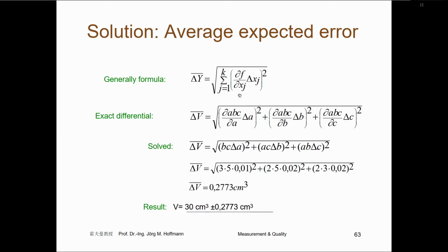But when we do not have a standard deviation, we take this other determined value, the delta of the error, and we calculate the average expected error. Here it does not work to double this. You do not know exactly how many percent are in this range. That can be 68, but it can also be more, especially with an error class, because an error class is every time bigger than a standard deviation.